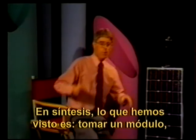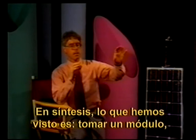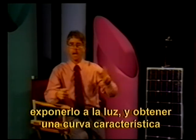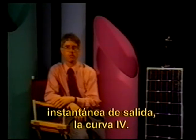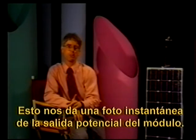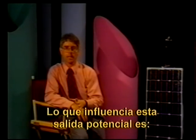So in summary, what we've looked at is taking a module, shining light on it, and getting an instantaneous output characteristic curve, the IV curve. This gives us an instantaneous snapshot of the potential output of the module. What influences this potential output?